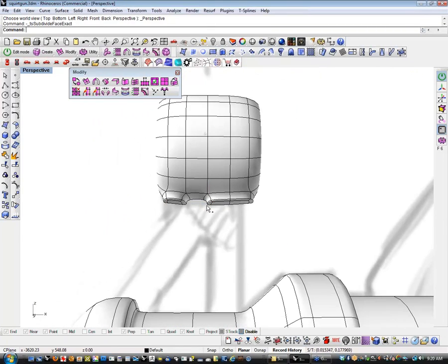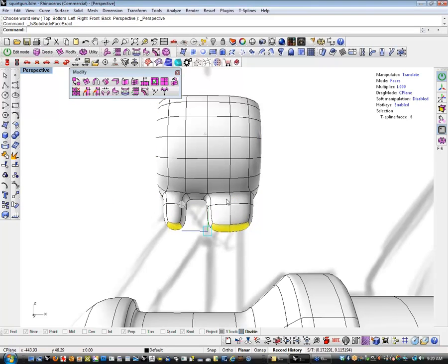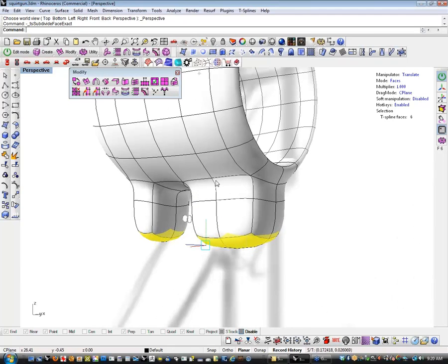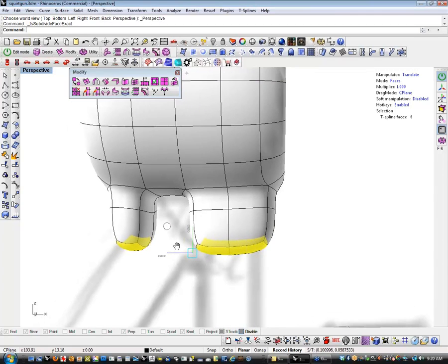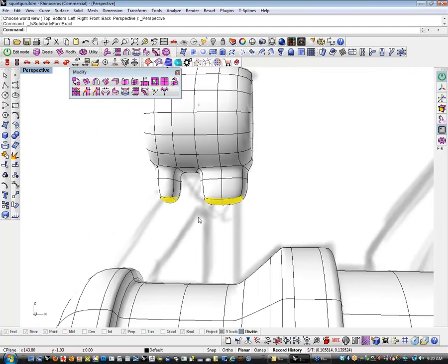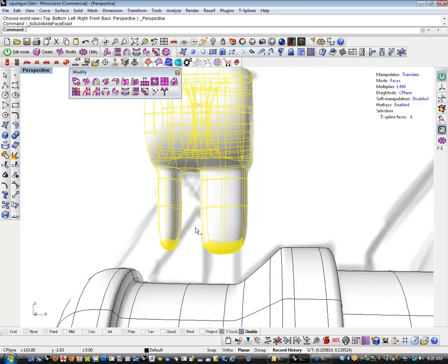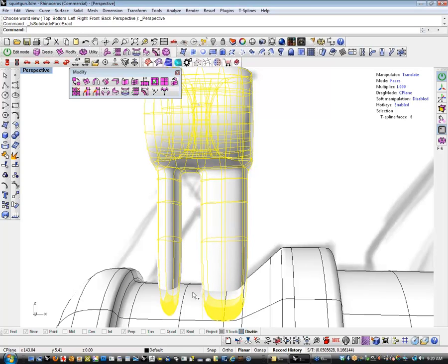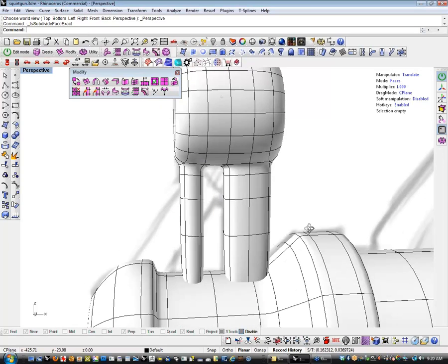alt drag. Now I always do a little extrusion first, because what that essentially does, if you think about this in NURBS terms, think about this as your fillet surface. So that first extrusion is essentially going to determine how much control you have over that fillet, and then the rest, you can kind of go from there.